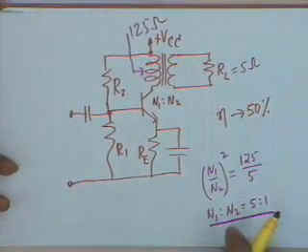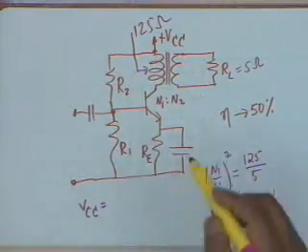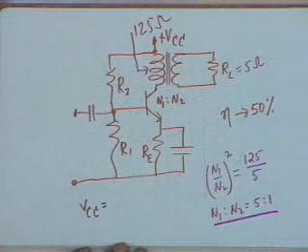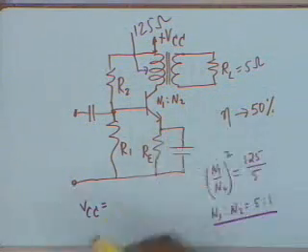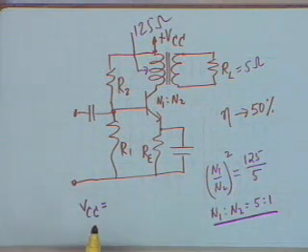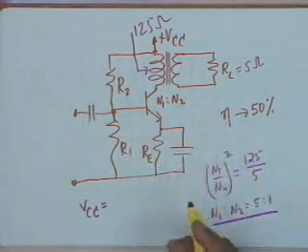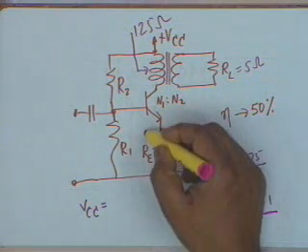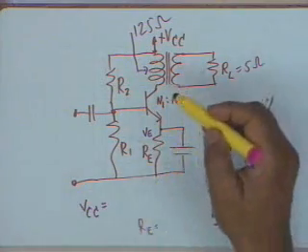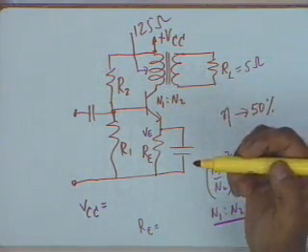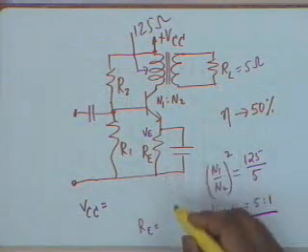Now, under this condition, what VCC shall be needed? Well, to determine VCC, you notice that the transformer primary, because of zero resistance, we assume it to be ideal, does not drop any voltage, and therefore the only drop that shall occur shall be across R sub E. And you can set this drop almost arbitrarily, and as I said, 3 volts, 2 volts, these are typical figures. If we set this at 3 volts, let us say, if VE is set at 3 volts, then obviously RE needed shall be equal to, the current is 0.2 amperes, 0.2 plus 0.2 divided by beta, but since beta minimum is 30, we can ignore that term, and therefore what shall be RE?